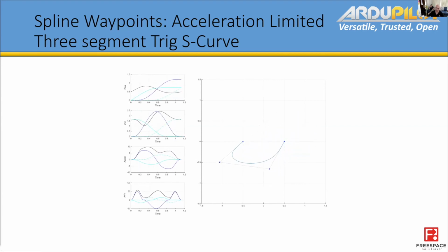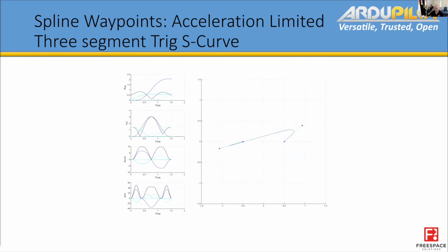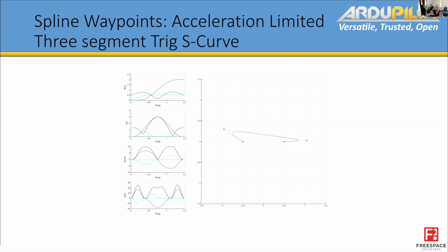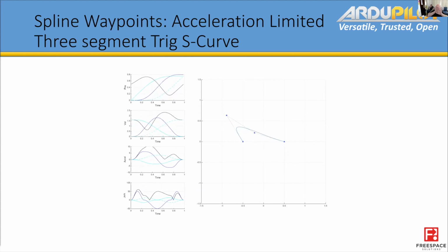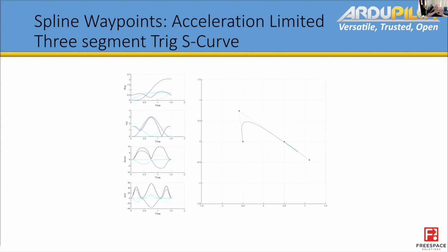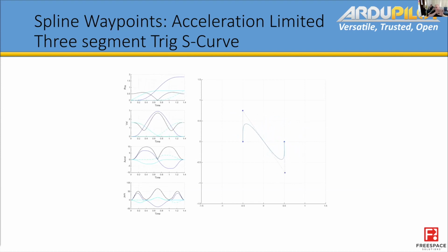And then we shift the timing of each of these so that as the accelerations from 2 consecutive segments are both coming up at the same time, if they increase beyond a certain point, we delay the second one a little until the sum of the 2 accelerations doesn't exceed our limit. And we're able to do that very easily and with very low computational cost as we move through.